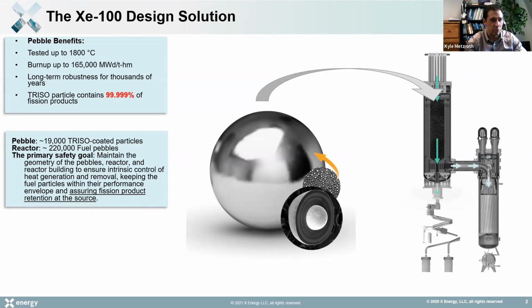There are 2 helium circulators, and a fuel handling system, which continuously refuels the reactor. And then we also have, not shown in this picture, a reactor cavity cooling system, which is our safety related means of removing heat in the case of a design basis accident. The plant has been designed to rely on inherent safety. So there are no active components required in order to demonstrate acceptable performance under accident conditions, both in terms of heat removal as well as reactivity control.